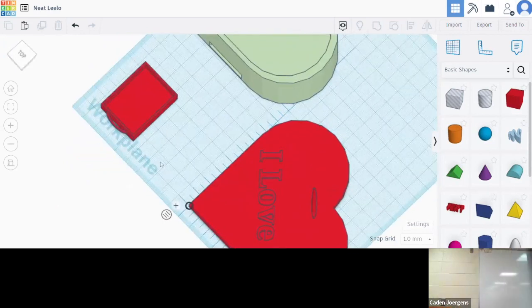One of the reasons I had this inner box up 15 is because I wanted to give 3 millimeters of space between the bottom of the hole in our box and the top of the hole that we put in. That way there's not just a straight hole to the bottom, and it has some integrity. You don't want to make things like 1 millimeter thick because that's ridiculous for integrity.